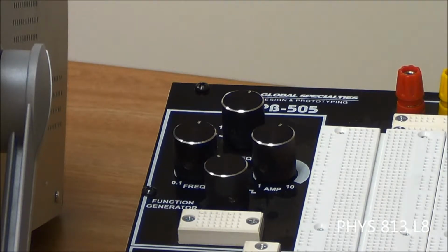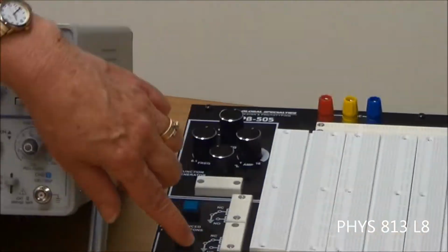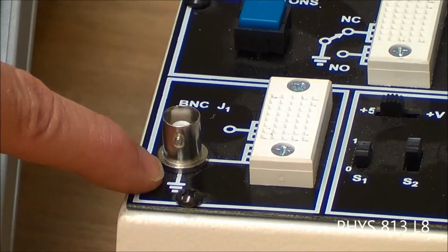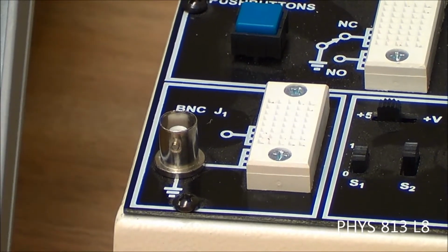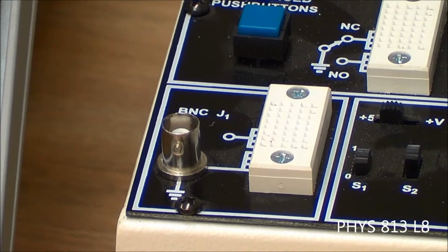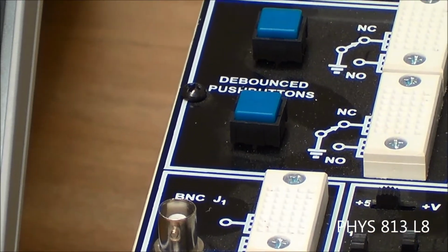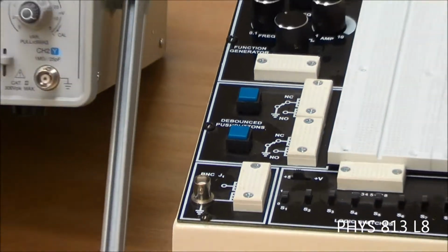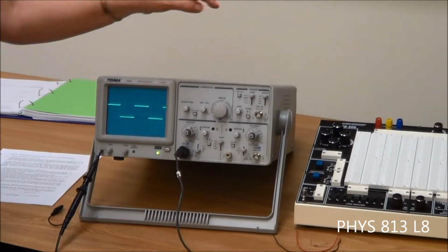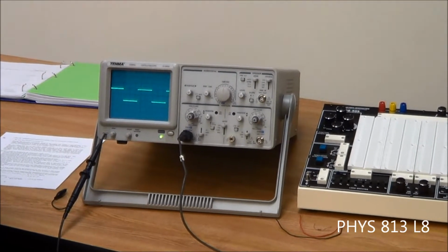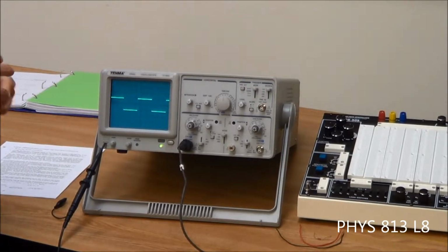The other thing we need to know something about is down here in the lower left-hand corner of the circuit board. There's a little silver thing, and then there are 3 parallel lines that sort of form a triangle. This is the standard symbol for ground. Now, we do have an alternating circuit, but there still is ground. And this may be a little bit confusing, but the main thing we're going to keep track of is that ground for the oscilloscope and ground for the circuit board has to be the same place. And that's why we're going to have to make sure that we connect things properly and make measurements when things are in the proper place. And I will explain that as we go along.